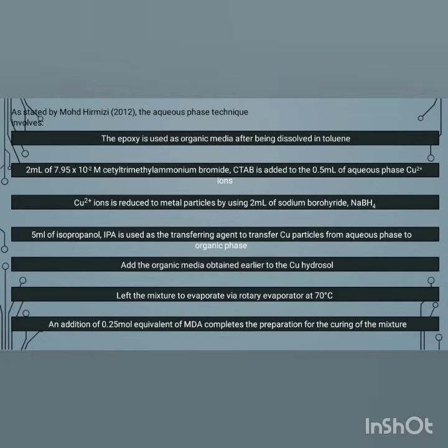The mixture is left to evaporate via rotary evaporator at 70 degrees Celsius. An addition of 0.25 mole equivalent of NDA completes the preparation for the curing of the mixture. The curing process is held for 4 hours at 150 degrees Celsius for the complete forming of the composite.